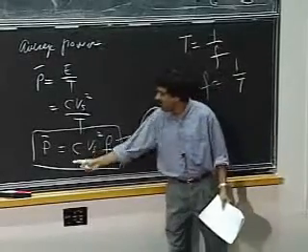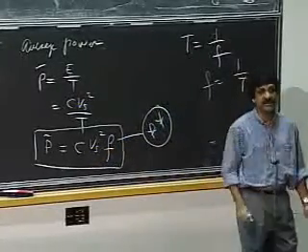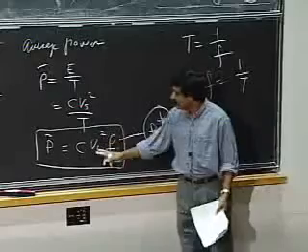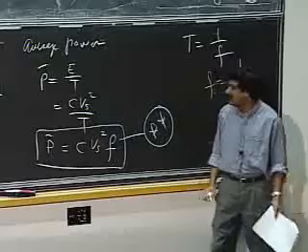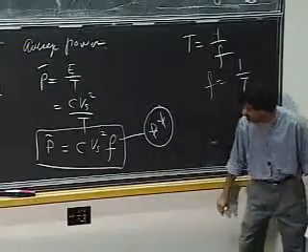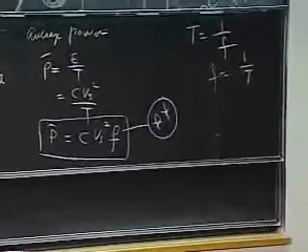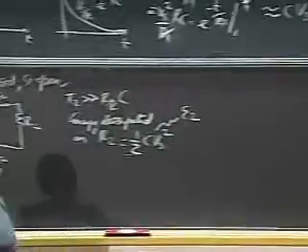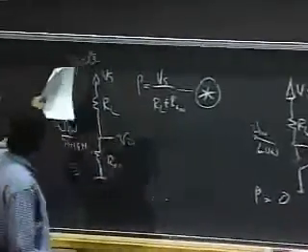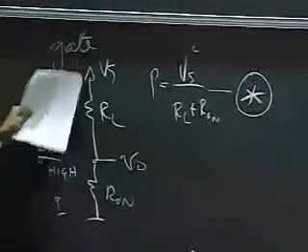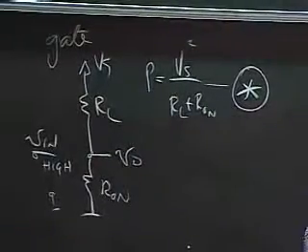And similarly, the average power also relates to the value of the capacitor. If C is larger, I dissipate more energy. And the same way with the voltage. If the voltage is higher, then the power in that period, or the average power, relates to Vs squared. So spend a few seconds staring at the two expressions. This power here relating to just this connection between the power supply and ground, and that power out there relating to charging and discharging capacitors.